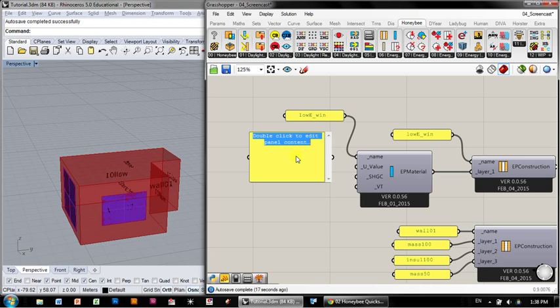And let's do a very good assembly. This includes the frame, by the way, so this is both the frame and the glass. So maybe like 1.3 watts per meter Kelvin for the U value. That would be a really good thermally broken frame and a very good double glazing with a Loisos film.